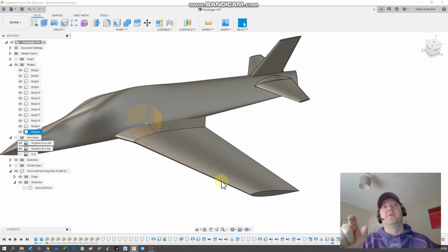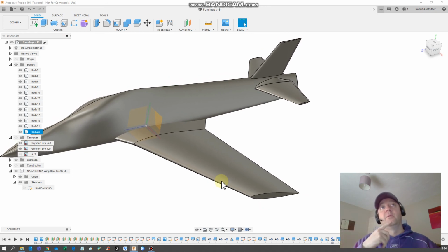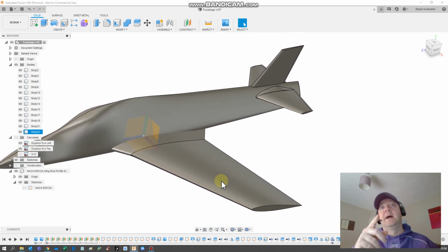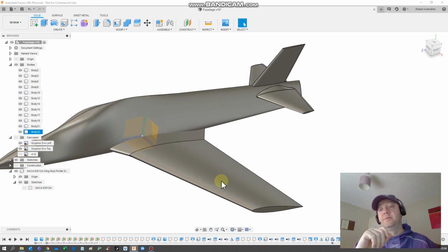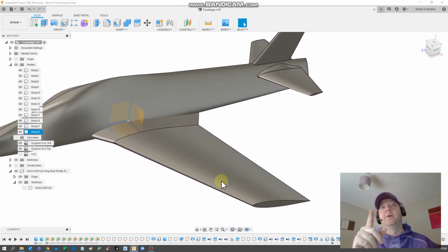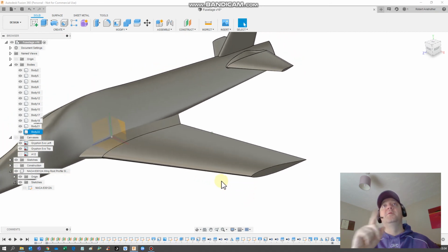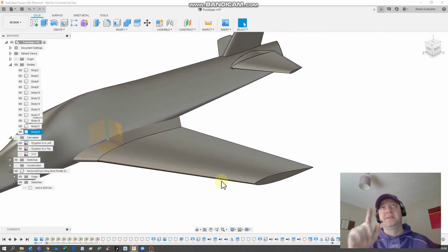So I'm going to stop this video here. I'll start another one where we can look at maybe changing the tip with this method. If you were to use the same method as I've used on the tailplane, it's a lot easier because you can actually manipulate the end profile around its center point. So you can actually twist it by 3 degrees if you wanted to add washout.